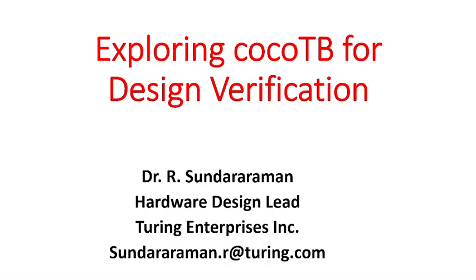Design verification is a process of developing test benches with stimulus generation and a checker. The stimulus generation generates various test cases which are applied to the inputs of the IP being developed, and then the output of the design is taken by the checker, where the checker logic ensures whether the expected output comes at the output or not.